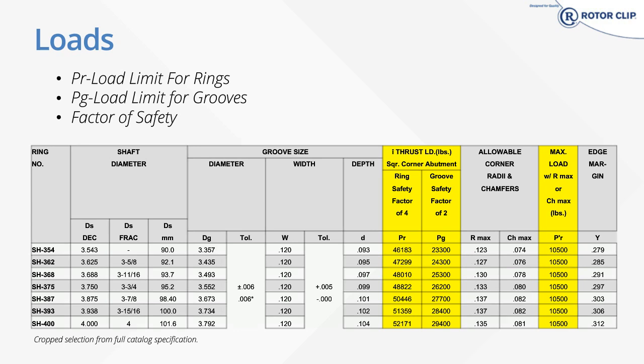The groove stays where it is, but an example of a little bit of fluctuation in the ring loading is if your retained part is loading unevenly on the ring. You may get an earlier failure than if you had a precise 360-degree contact. So with a little bit of variation, we up the safety factor, and hopefully you never have any troubles.